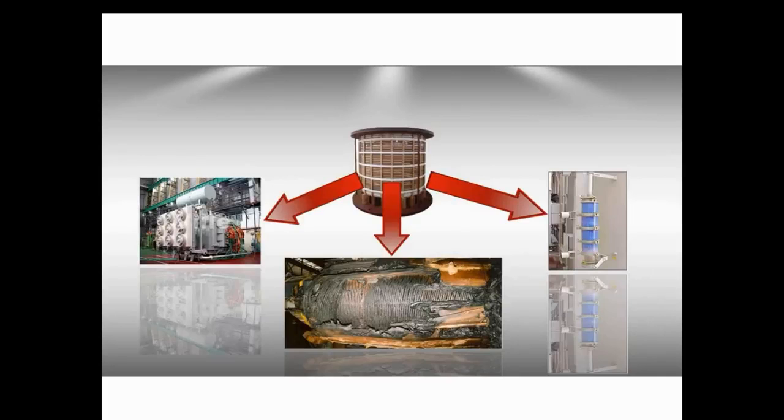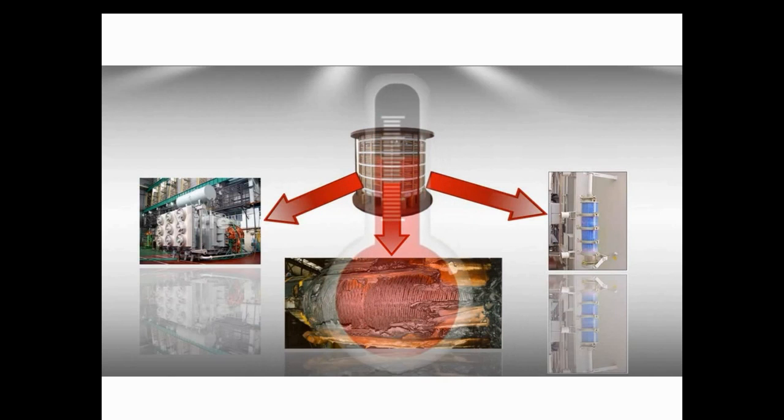Moisture left in by the manufacturer. Moisture incurred by thermal degradation during service life. In other words, as the paper oxidizes, it produces moisture. That's why there is a moisture increase while the transformer is aging. Moisture absorbed through unmaintained breathers.